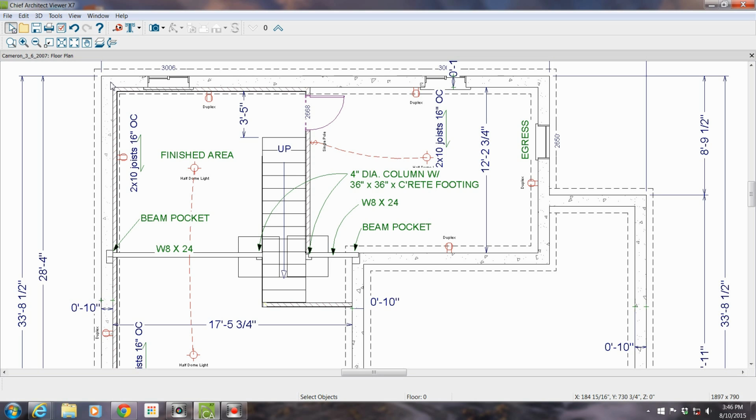So let's start on the outside. This wall right here, this space in here with these little triangles and these dots, that is a foundation wall. Now on blueprints, even on hand-drawn ones, they note foundation walls with these little triangles representing stone, I would imagine, and little dots and stuff. So that's always going to be your foundation wall. And here's a window well inside your foundation. So you can see that goes all the way around.